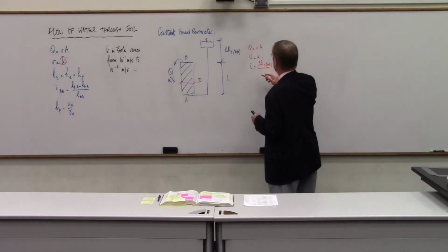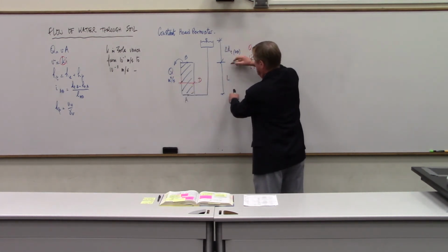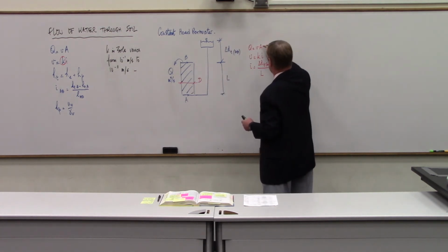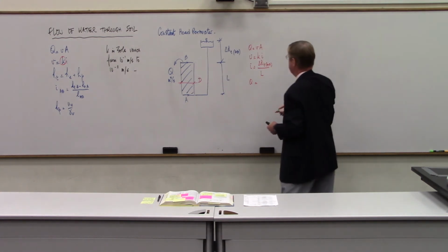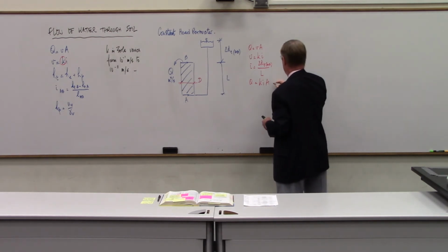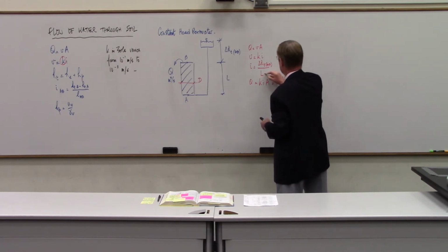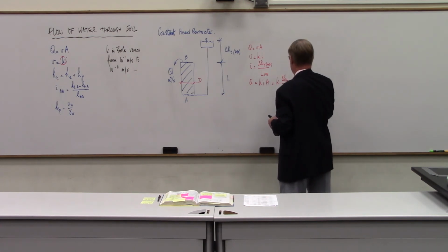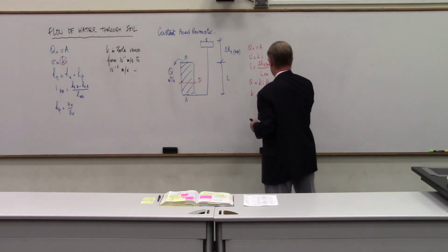And so if you regroup everything, because you're measuring Q, delta HT, L, and then you know the diameter D, you have in the end Q equals V, that's KI times A, and I is equal to delta HT, I'll drop the AB, over L, times A, and so therefore K is equal to Q times L over A delta HT. Okay?